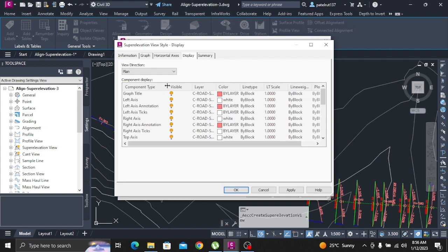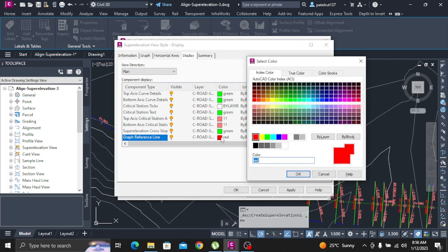Change the cross slope between superelevation curves. Pan to the left until you see the grip near station 1+000.00. Hover the cursor over the grip. Select Move both left and right. Enter 4. The cross slopes of both the left and right shoulders are updated.